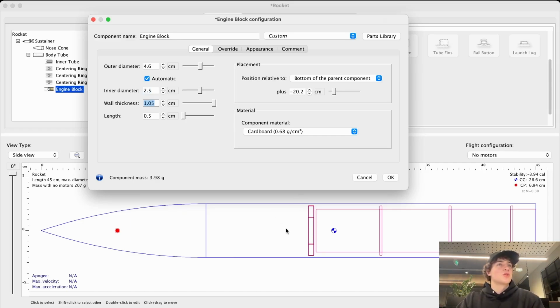Importantly, especially if you're making your L1s, your smaller scale rockets, we want to make sure we've got room on these two sides here to attach some way for us to ensure our parachute is going to stay attached to the body after deployment. If we don't do that, we'll shoot the parachute out and it's not tied to anything. I'm sure it'll come down nice and slow, but our rocket, on the other hand, will not.